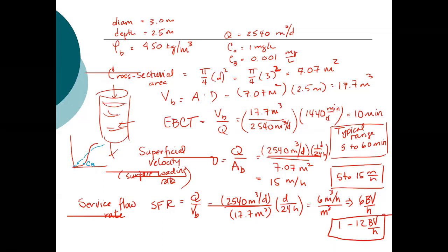So you can sometimes operate a system like that. The carbon that they were using, because it's difficult to remove the PFAS compounds, is expensive. So you want to protect that column. So that first column essentially protects your polishing step and your second column.